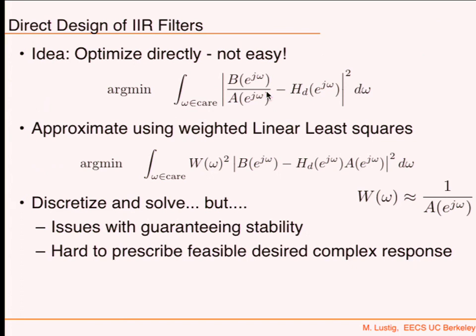Okay? And we'll get to what even nonlinear phase means. If you don't care about it so much, then you might as well use an IIR. Okay, so they are absolutely used in the systems. They're not as often needed as they used to be. Especially today, if you're going to use a large FIR filter with overlap and add FFTs.